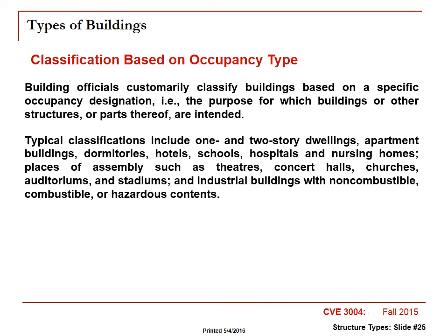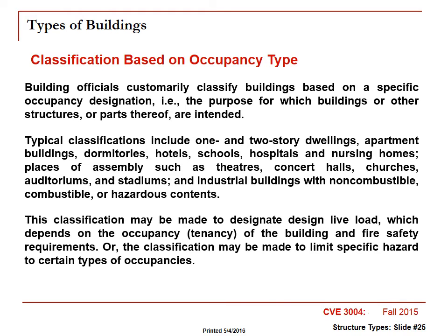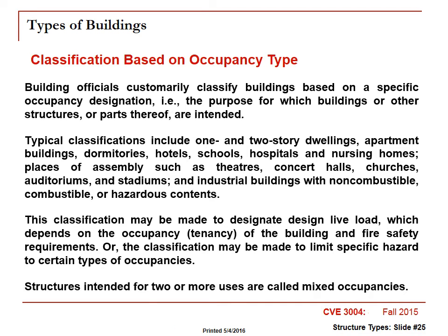So instead of trying to represent a classroom full of students based on everybody being 150 pounds and there being 45 students, that classroom is going to have a uniform live load floor loading. That is going to be different than the live load floor loading in a house, and that might be different than the live load floor loading in a theater.